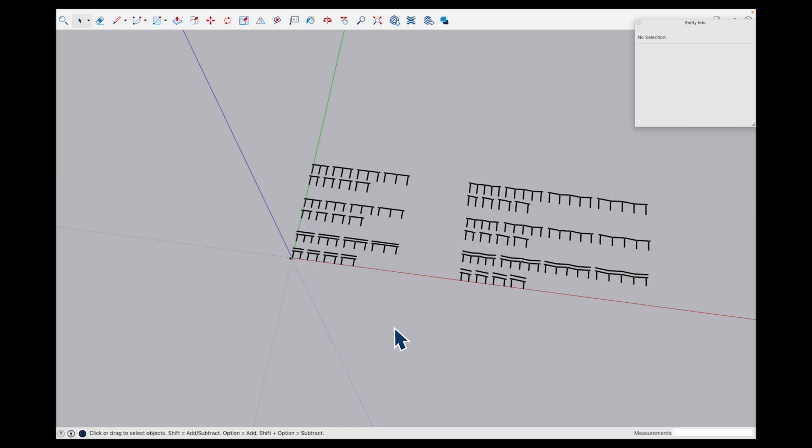What I want to show you here in SketchUp is that these lines I have down here are what's called my axes. I have my X, Y, and Z axis, and that represents the lateral, sideways, and vertical axes within SketchUp that really drive this program home and help you orient yourself. Here we have different items I drew with the pen tool, and once you draw something with the pen tool, it closes and it gets this little fill. That fill means that the object isn't solid, however, but if I were to push and pull on that, I would be able to get some mass, and we'll start that shortly.